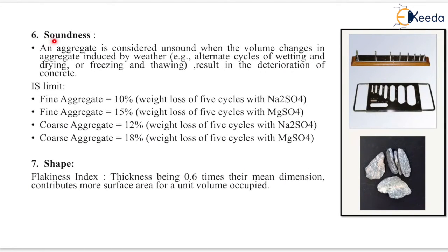Now next is the soundness. An aggregate is considered as unsound when the volume changes in aggregate induced by weather, that is alternate cycles of wetting and drying or freezing and thawing, result in the deterioration of concrete.